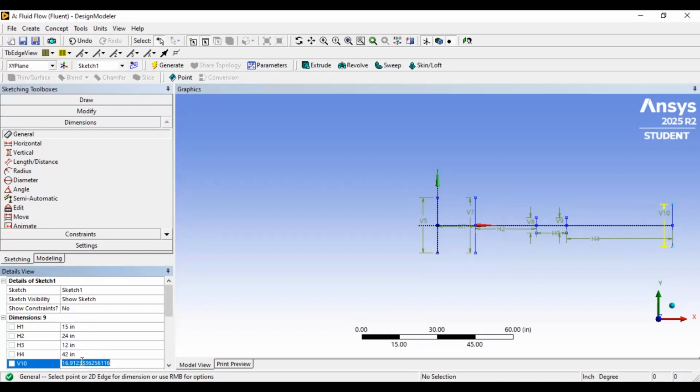So what we do is take the tangent of the angle, which equals the length that we're trying to find over 42 inches, which is the length, and we solve for L. We get approximately 2.2. So now to find the height, we take 6, which is the height of the test section, and add it to 2 times that length that we found, to find the total length of the test section, of the end of the diffuser, sorry. And that comes out to be 10.4023. I think it rounds down. Yeah, that's fine.